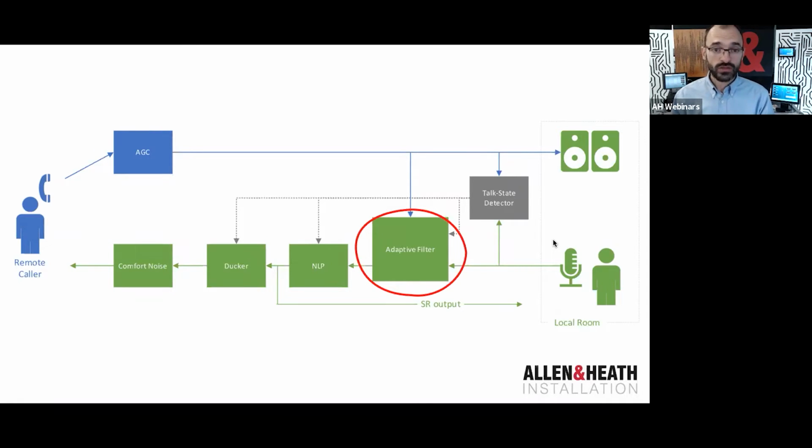Another trick that we use is normalization. Normalization adjusts the filter update rate based on the amount of energy in the signal. Without normalization, the system would be very sensitive to operating level. So small signals would not be able to produce significant changes to the filter, and very hot signals would cause the filter to become very unstable. So that's what normalization does.